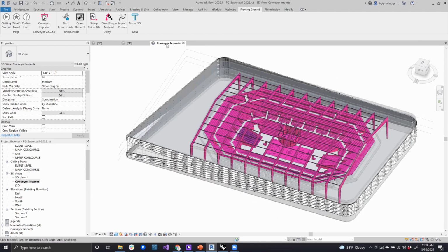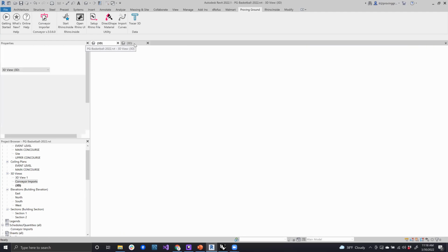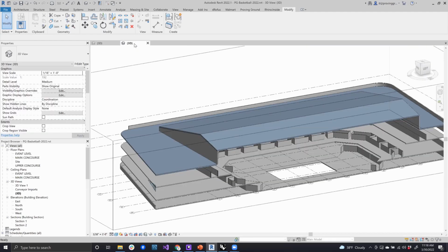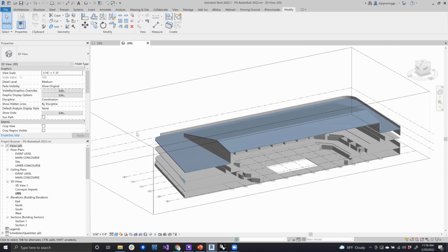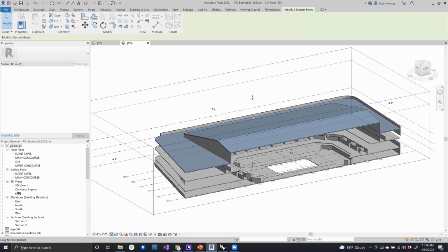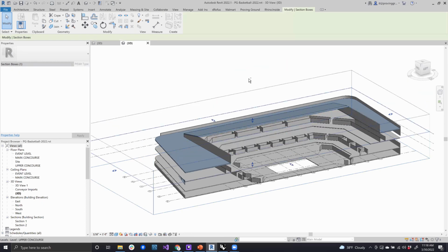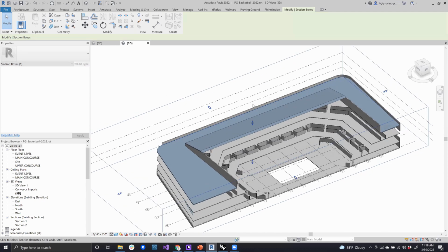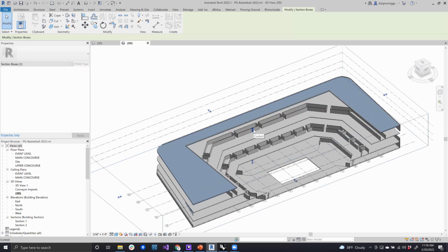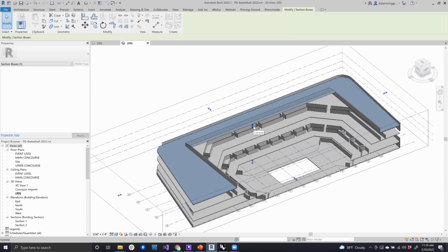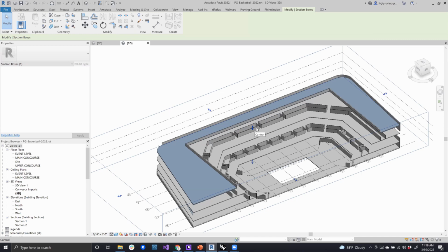So let's talk about how we get here. I'm going to go into my 3D view here in Revit, and I'm going to go through a set of steps to start bringing some objects over so we can get a feel for how Conveyor allows for element transfer to occur. And there are a variety of different techniques to support element transfer. Based on your project and the requirements of your project, you may choose one pathway or another based on convenience or ease or usability.